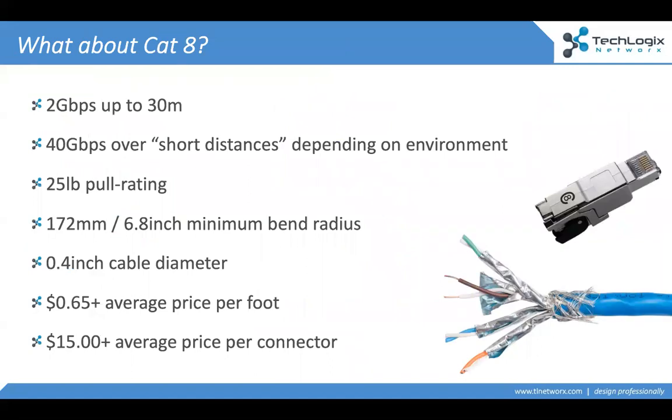Now, what about Cat8, okay? Because we're getting more conversation, more questions around Cat8. And frankly, this is an area that a lot of integrators are starting to move toward. And the big reason is because, yes, there's a perception that we get more bandwidth out of it. And there's a comfort factor, right? We know how to terminate twisted pair. So if I can get another twisted pair cable that can push that bandwidth up more, great, I'm going to go for it.